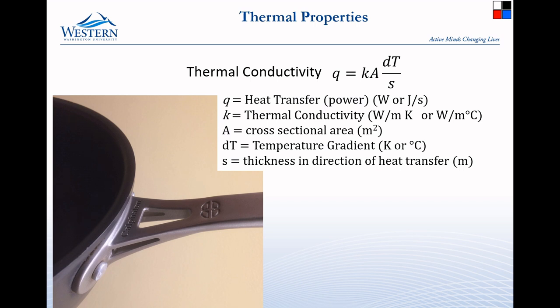So by choking the cross-sectional area, we don't allow the heat to even come out to the handle. We slow down the rate of heat flow such that this handle is plenty enough mass to absorb the heat and dissipate the heat by convection and radiation, and that way we can grab this metal handle over here, and it will also help to keep the heat in the pot, in the pan at the same time.